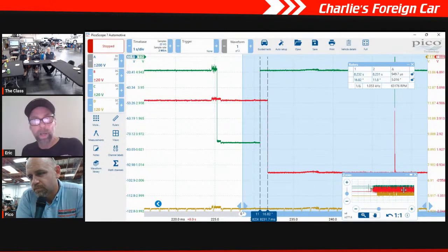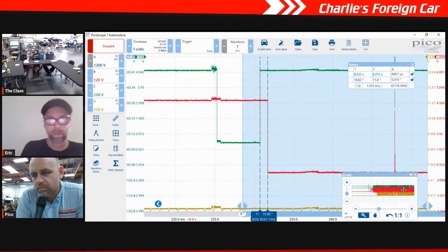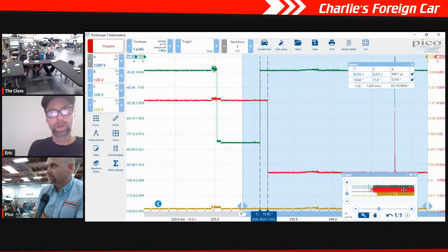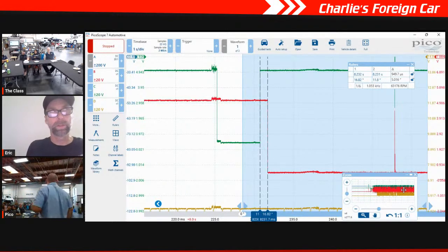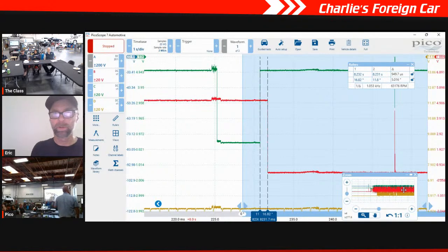Okay, so this is not adjusted, and when we go to the adjusted side, since the intake's the only one that's adjusting, what does it do? It's going to move closer to 0, correct? Comes back. It retards. No, it advances. Advances, right. It's going to be moving toward 0.